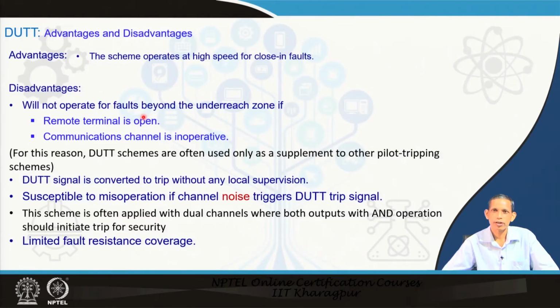If the corresponding fault is from the M bus side, as you have seen earlier, it will not go for a decision if the remote terminal is open, if the end side breaker is open, and if the fault is in that line. In that case, the M side will be observing it in zone 2, not in zone 1. So, you cannot exploit the advantages of the high speed protection or oscillator protection.